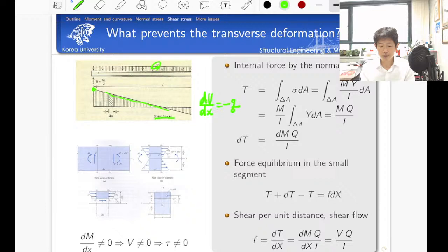Now we want to consider a small segment here, whose width is measured by dx, okay, dx. So let's exaggerate, let's zoom in on the cross section here. If you look at the situation here, let's say this is my coordinate x, and this is the position x, the reference position. At the reference position, there must be a reference bending moment and a reference shear force, isn't it? If we move my point by dx, then there must be a change in the bending moment, dM, and a change of shear force, dV, right? We must have some certain changes.